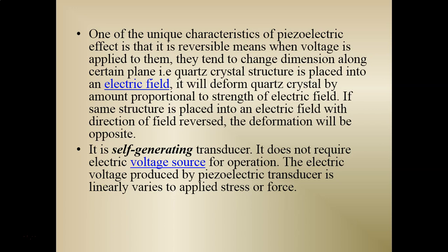And also it is a self-generating transducer. So what is a self-generating transducer? It does not require an electric voltage source for operation. The electric voltage produced by a piezoelectric transducer varies with the applied stress or force, depending upon how much stress or force we are applying.